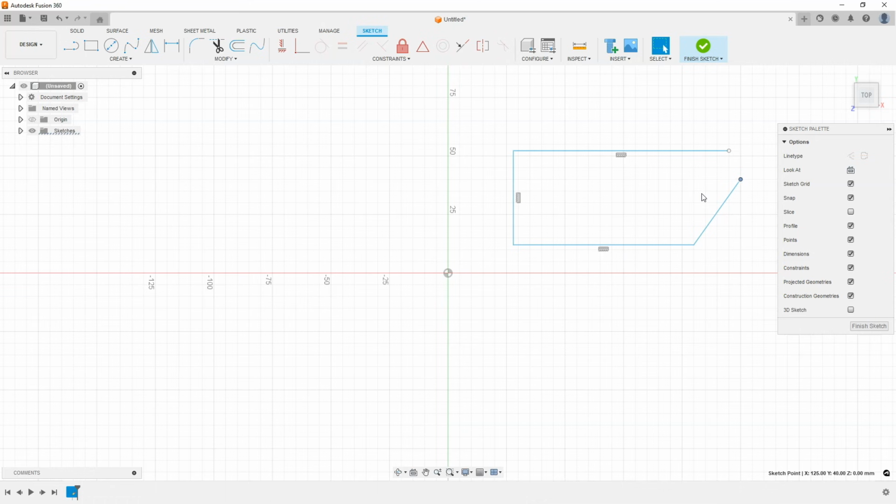And let's return to the form of the geometry before we deleted the constraints, and let's manually add the constraints that we removed. To make this line a vertical line again, select this line and select the horizontal vertical constraint.